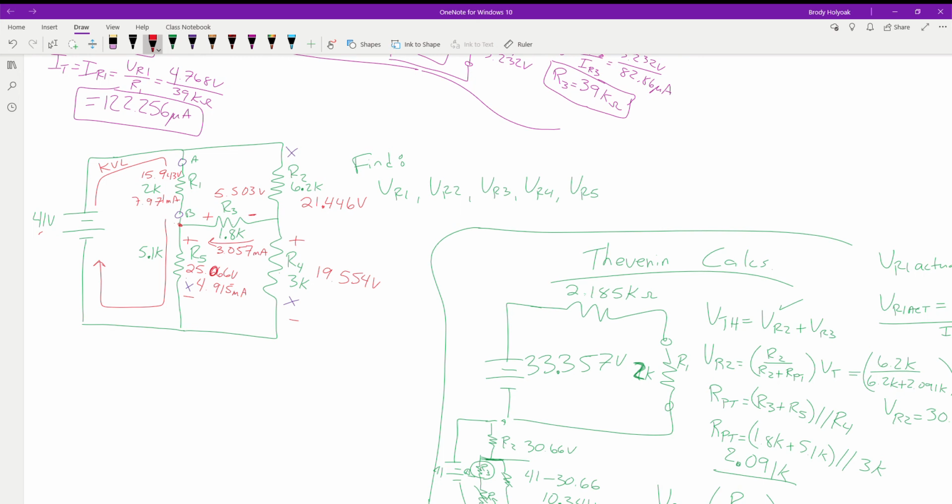So what we're going to talk about tomorrow is we're going to go through another current meter that offers us more protection when we are switching ranges. Because before, anytime we would switch the range, we're disconnecting the circuit, plug it in. So if we're in a 2 milliamp range and we suddenly start throwing 15 milliamps through it, we don't have our shunt resistor in place. So we could damage that meter just by switching our ranges.